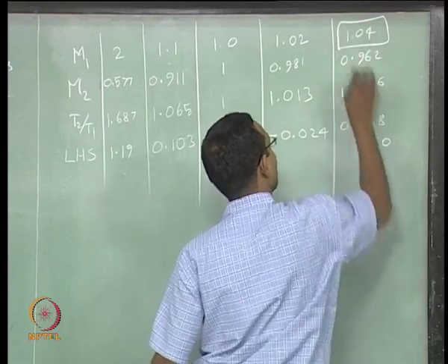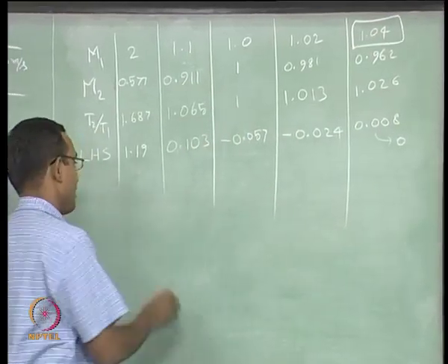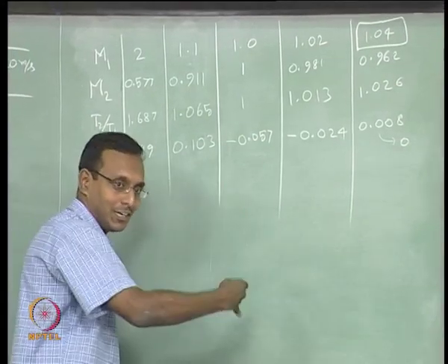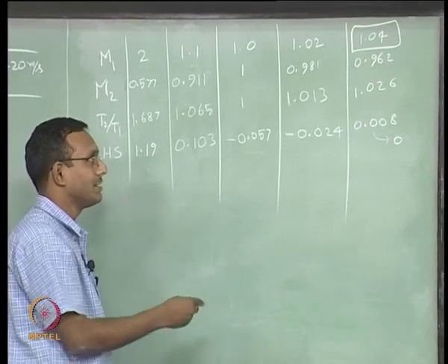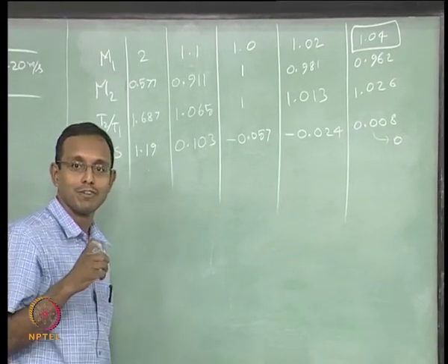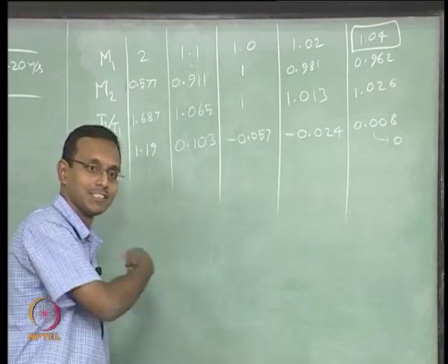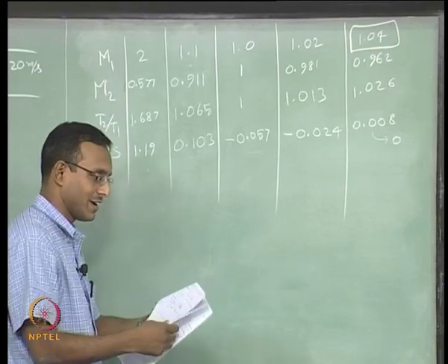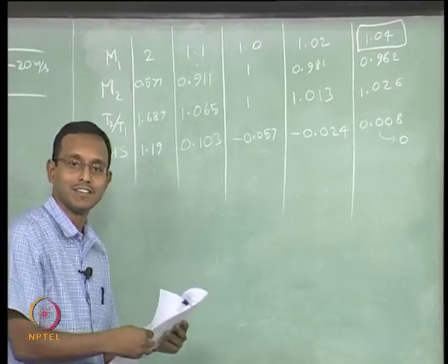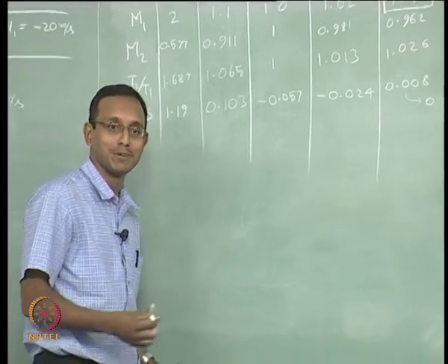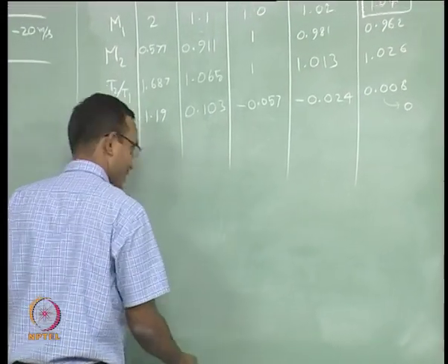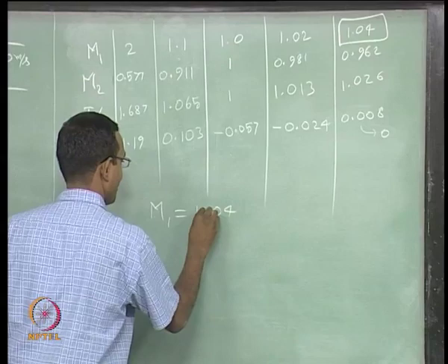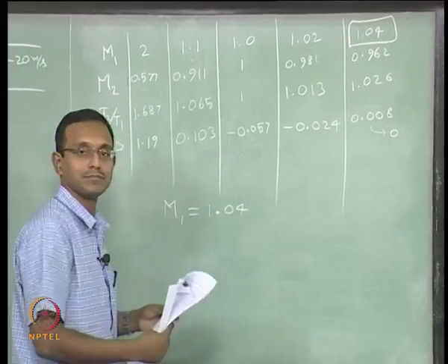So I am getting my Mach number to be this. Okay. If I stop a 20 meter per second flow in a duct with a sudden lid completely closed, no mass flow through it, then I will produce a Mach 1.04 shock going against the flow. Okay. That is what we know as of now. We will go and find the implications of it next class, because I have one more full page of implications because of this. We cannot go through that now. We will stop here with M1 equal to 1.04. We will continue the same problem next class at the beginning.